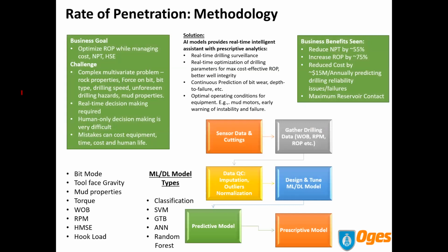So this slide essentially illustrates a possible methodology to maximize ROP. It's a little busy, I confess, and I apologize for that, but the ROP is related obviously to the speed with which drilling is performed, and maximizing it is one of the critical factors affecting the commercial success, obviously, of the drilling operation. So the rate of penetration prediction with mathematical models, as I mentioned, is somewhat helpful, but can we complement that with a machine learning methodology as well?